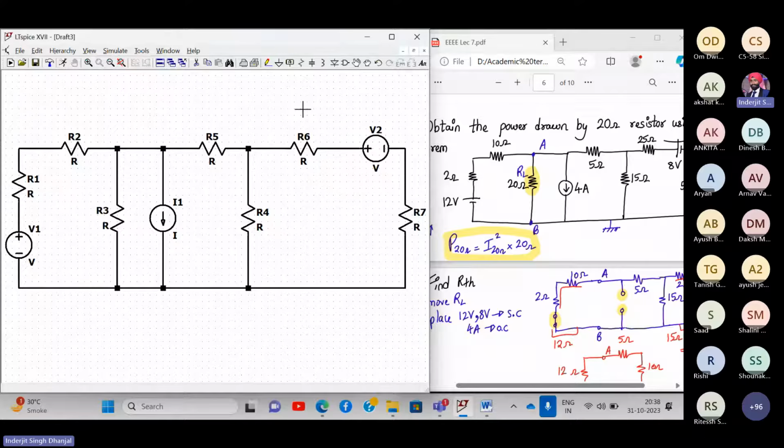Yes, sir. So great. Just one question, how to rotate? Control R. If you select any component, let's say I've selected it, immediately press Control R. And in order to place it on the schematic, one click. Okay. And in order to move the next component, move it around. And then I press Escape.